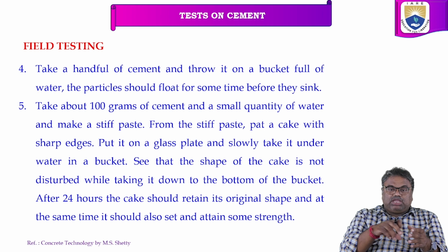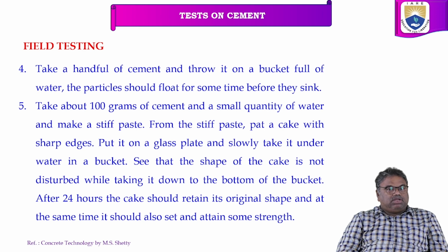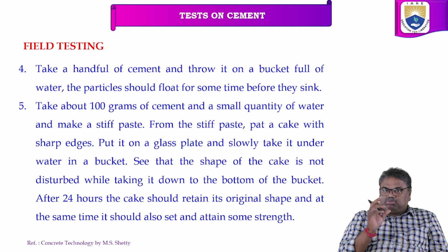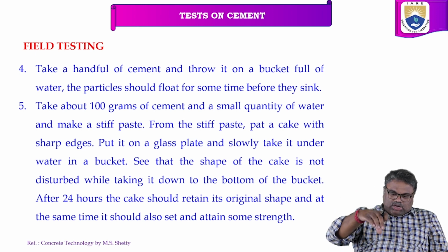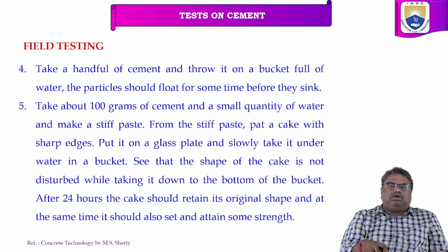See that the shape of the cake is not disturbed while taking it down to the bottom of the bucket. You should not disturb the shape. Slowly dip the entire cement cake into the bottom of the water, and you should see that the cake shape is not disturbed.